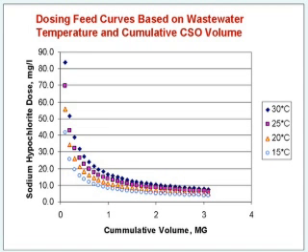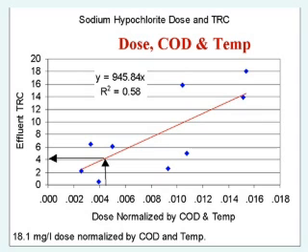These are two totally different systems. But if you look at an outer envelope of how the pollutants occur, for example, that green line, that's just a power equation through the data, laying on top of the data. You use that power equation with your dose-kill regression equation to prepare an algorithm that you can then calculate and put in your SCADA system, the feeding curves, the chlorine or oxidant feed curves to control your feed pumps to cause your disinfection.